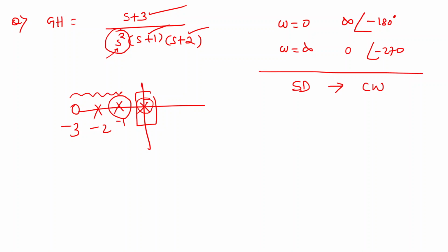Okay, in control system terms, I am telling you. So nearest pole: one is at the origin, s equals minus one. Of course, you can see two poles and one zero there. Which one is nearer to the origin? This, minus one, that is a pole, sir. Don't consider other terms. Only see which one, pole or zero, is nearer to the origin. Pole is nearer to the origin. That's why clockwise.